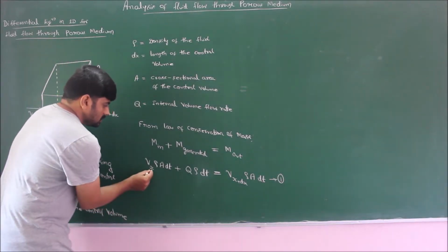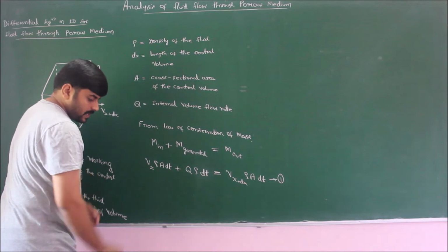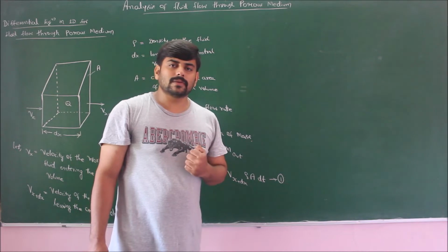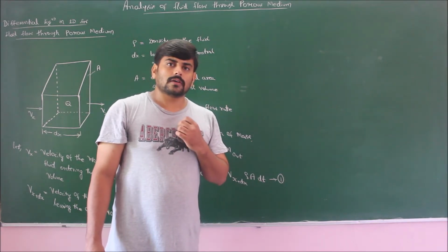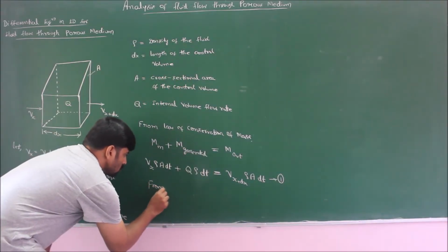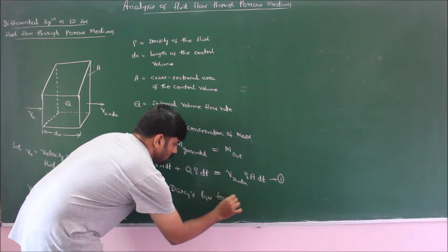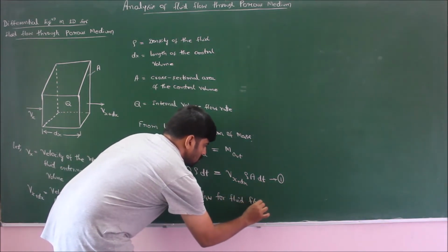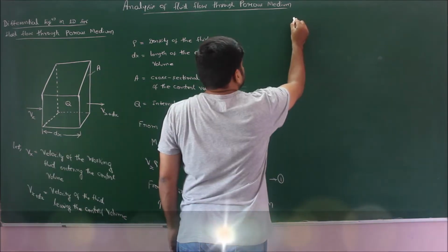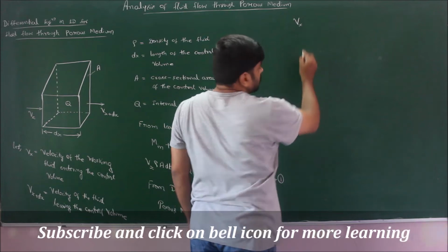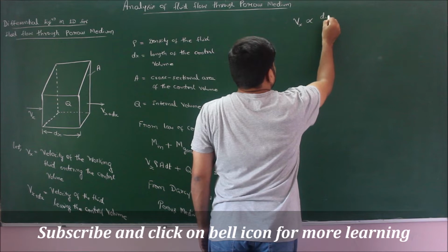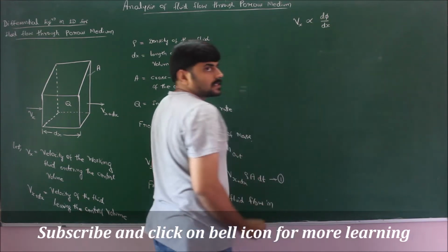Now, the velocity of the working fluid entering the porous medium can be analyzed by using Darcy's law for fluid flow in porous medium. Darcy's law states that the velocity of the working fluid in the porous medium is directly proportional to the hydraulic gradient d phi by dx.